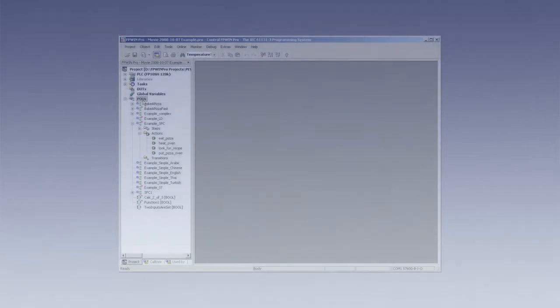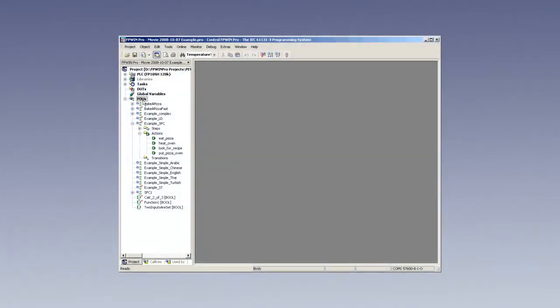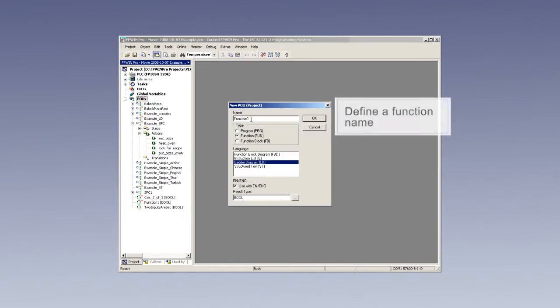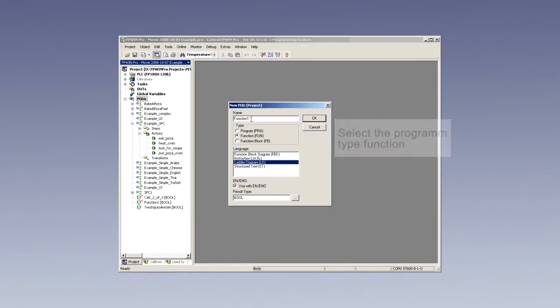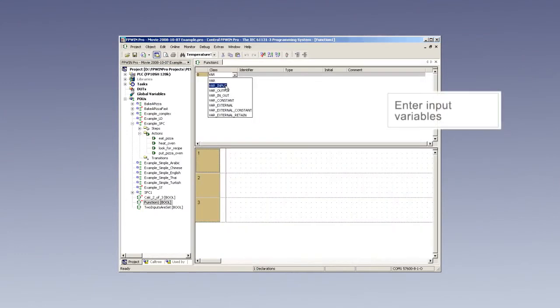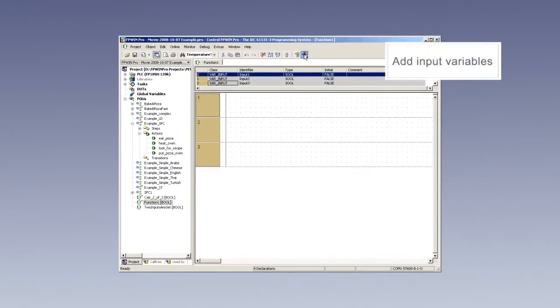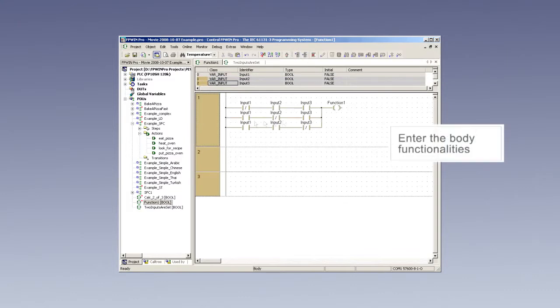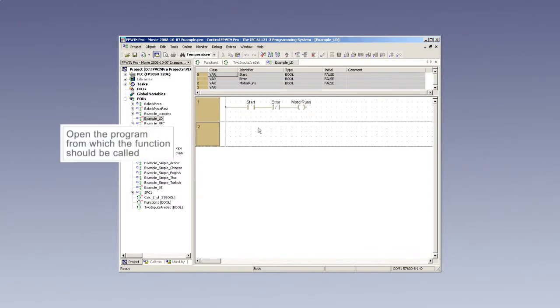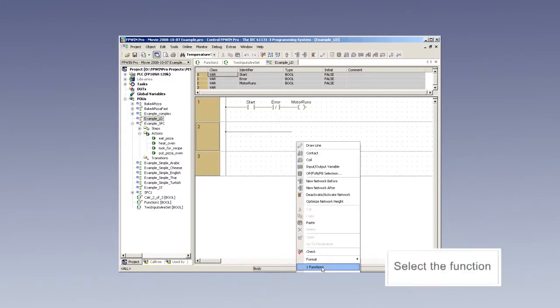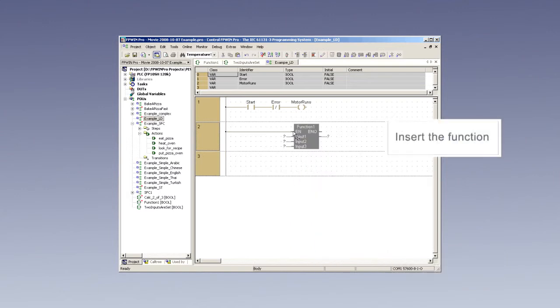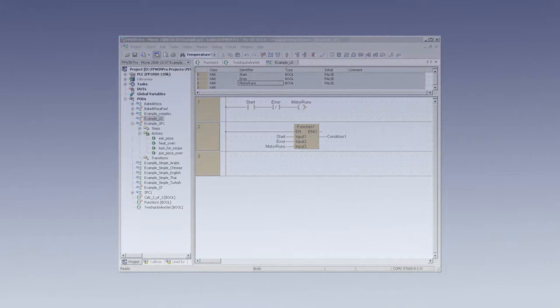The Program Organization Unit (POU) concept of the IEC standard enables you to program your own functions and function blocks. The POU consists of a header with a variable interface and the body with the program code. The variables in the header can be used by the function or function block. The program in the body must be developed only one time, tested only one time, but can be reused infinitely in PLC programs. This saves time and errors.